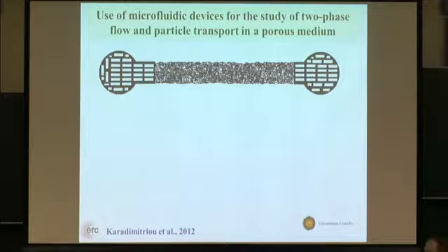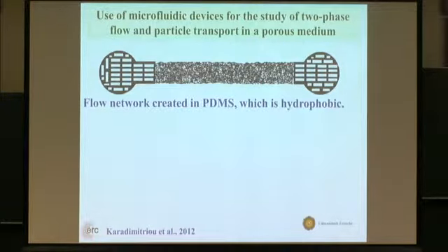We studied these, among other ways, using micromodels. A micromodel is what they call a microfluidic device. You see an image of it here. These are thousands of pores made in a transparent slab. The slab is made of PDMS, and then we put another slab of PDMS on it, and we can seal it.